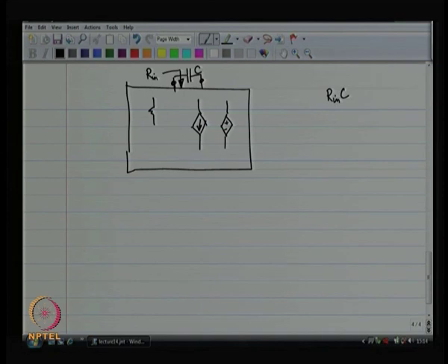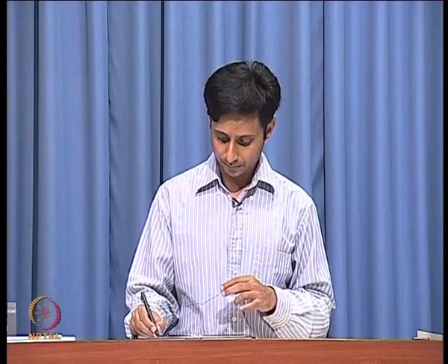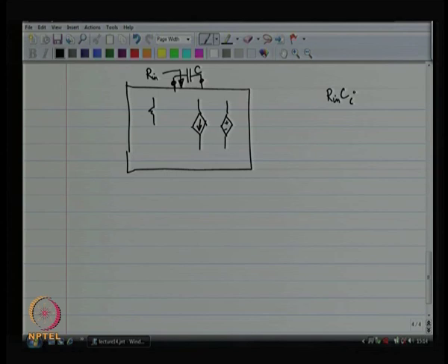You do the same thing for all the different capacitors in your network and tabulate your results. Okay. Now, the claim is that the 3 dB bandwidth is the reciprocal of the sum of all of these time constants. So, these are called the open circuit time constants.